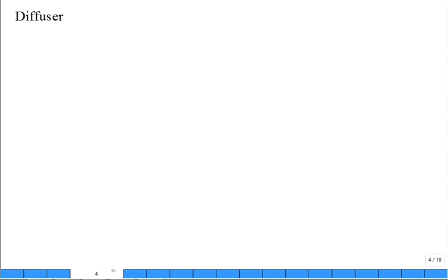The opposite of a nozzle you may not have as much experience with. It's called a diffuser. We have a lot of diffusers in application, maybe not as many in engineering applications as nozzles. We have a lot of nozzles in a lot of places, but there are some diffusers. What does a diffuser do? Usually it's increasing the area. I'm exaggerating the increase in the area. What would it do to the speed of the fluid as it goes into a larger area? What would the velocity do? It would slow it down.